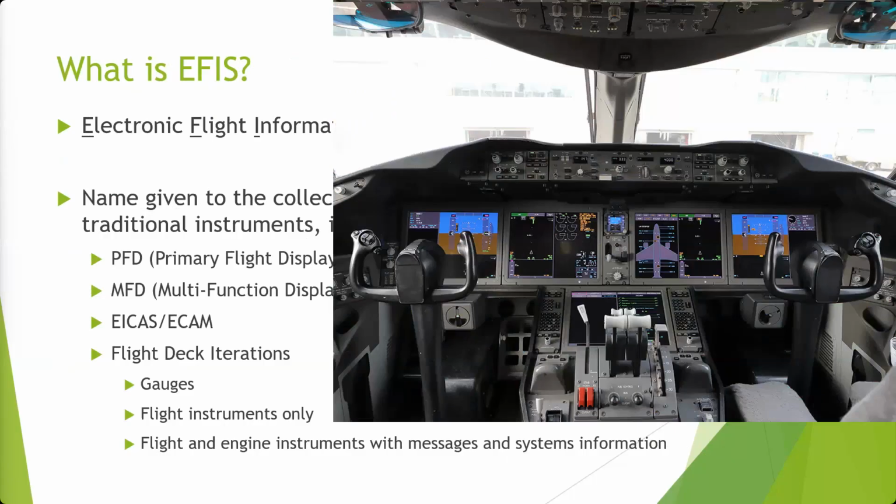So you have primary flight displays. You can have navigation information here. They kind of split them. Here's your primary ICAS display. Here's systems. Here's the co-pilot secondary display, co-pilot's primary display. You've got yet another whole systems page down here. So you can put information here and here. Actually down here, you can put checklists on the lower display. So now their checklists are built right into the plane instead of having to pull out a book every time you wanted to go through a checklist. Right? Yep, that's just technology enabled it.